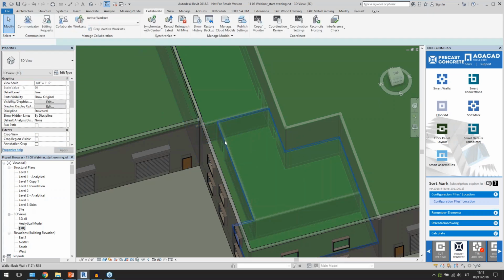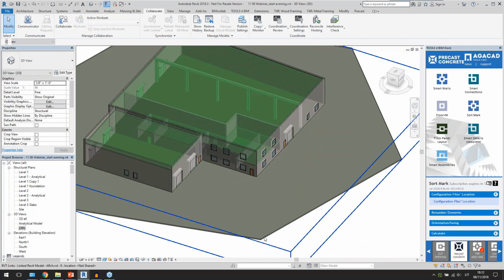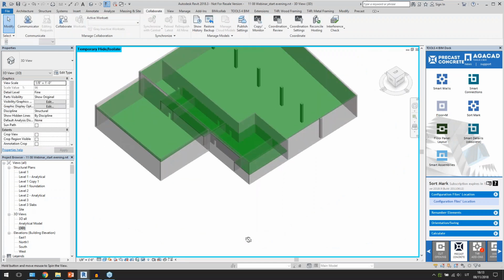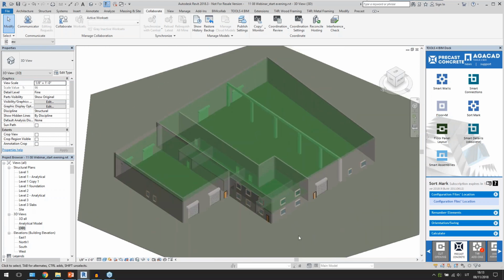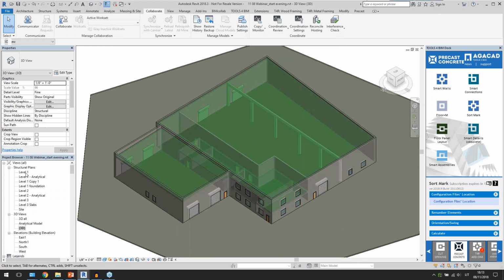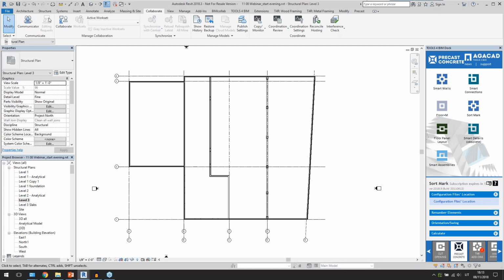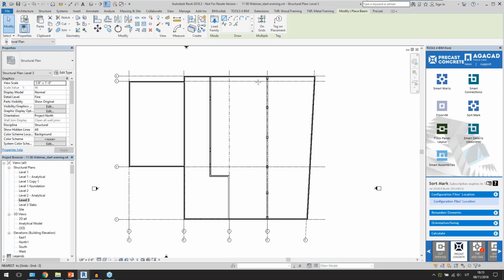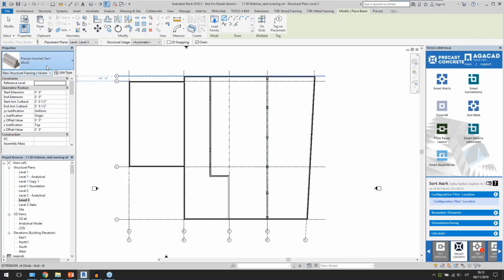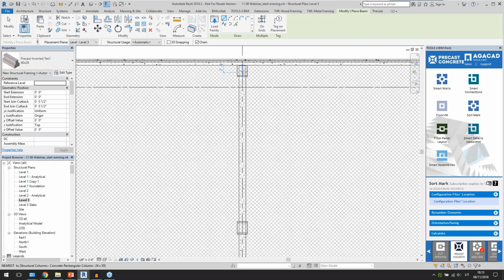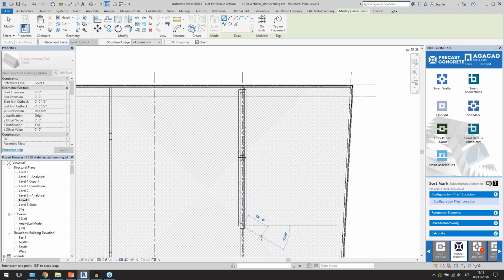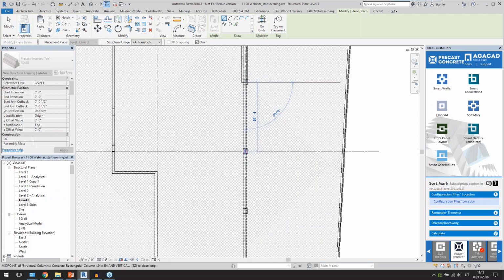So I got this already. So like this, now it should be better. All right, like this. So good. So I had my elements which I wanted to have. Now I don't have beams, so for that I will go to level 3 and just select the beam command in Revit. Pick the type of the beam which I want to use. Yes, and then I just draw it like this, like a chain of elements on my beams, on my columns.